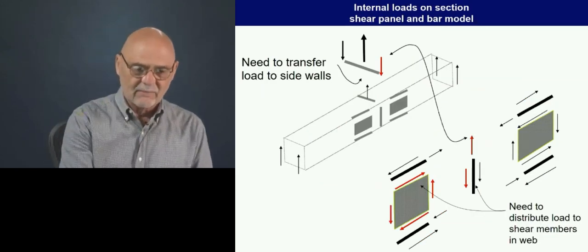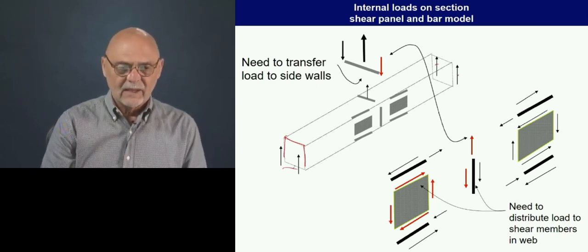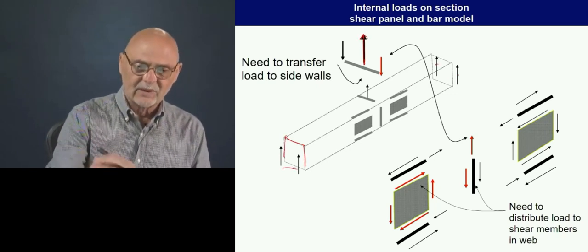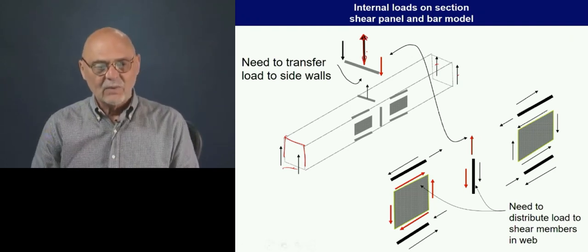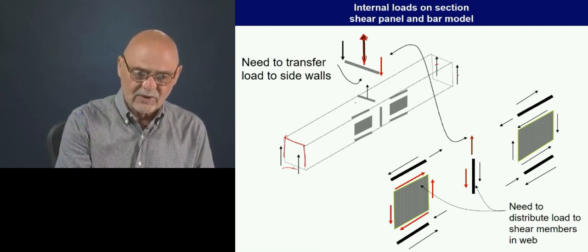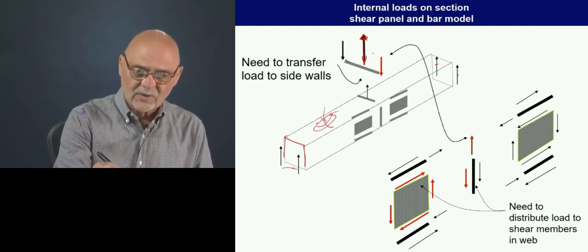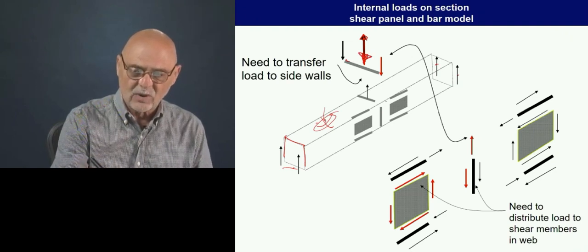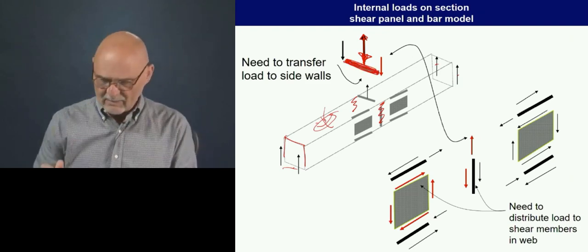Here is a model of the beam that we're just supporting on the ends. And here's the load that we're applying. Here we're showing it pulling up, it could be pushing down. What we're showing is a need that we somehow not load this very flexible plate here. We know that that's going to really distort. So how can we get the loads from this point out to the sidewalls of the plate? That's the first principle here. We need this kind of a rigid little member here.